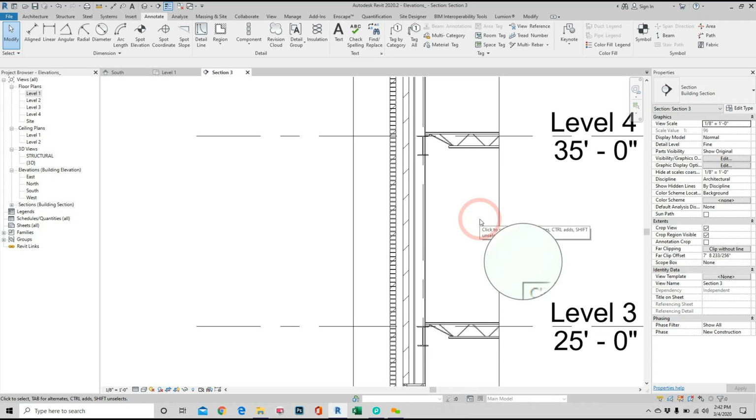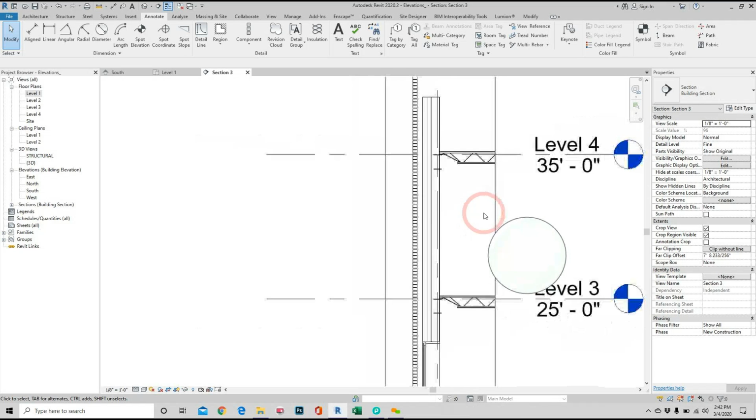Okay. That doesn't mean I cannot change it. I may have to have a stone or something like that. Professor Ackerman made a comment that he didn't mention, but I'll mention it now. If you want at least an elevation, keep coursing in 8 inch increments, right? Because it would always fit within 3 bricks. So that's one rule of thumb that you can use as you are designing.